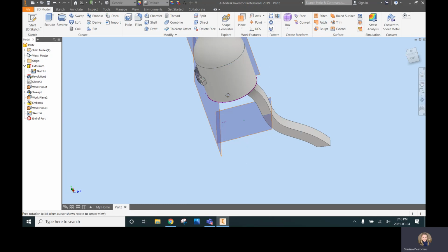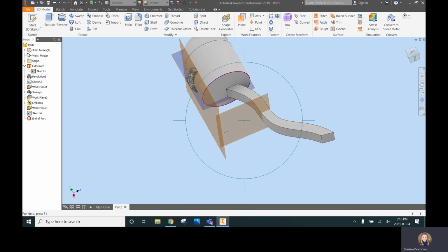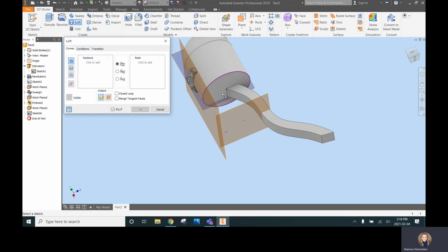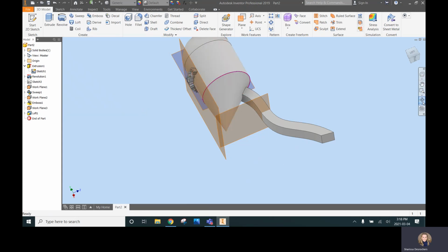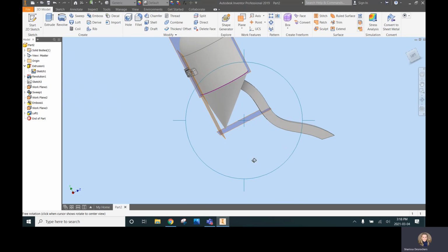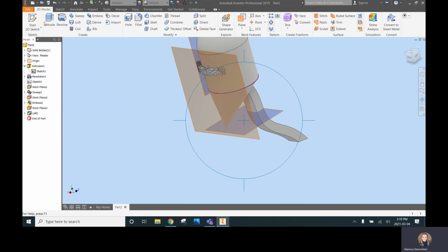So what you can do now is take this shape. We can do a loft, and you can go from this shape and loft to this shape, and then it'll create a solid between those two. And we want to do point sketch and then okay. And then it kind of made a cone. But you can also have multiple levels. So you could have this shape, the circle, and then a rectangle, and then a point or 2 points. If you wanted to give the robot 2 little pointy legs, you could do 2 points and then go from the circle to the 2 points. Or circle to smaller circles. Anyway, I'm just showing you some of the more advanced creation tools.